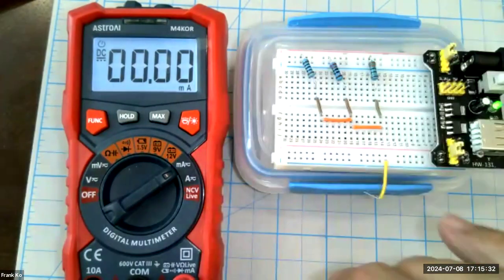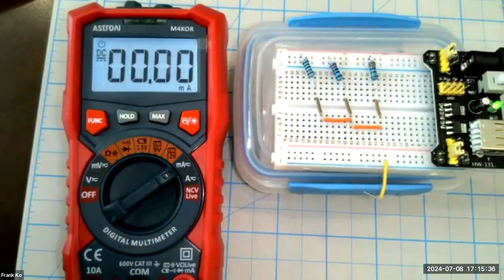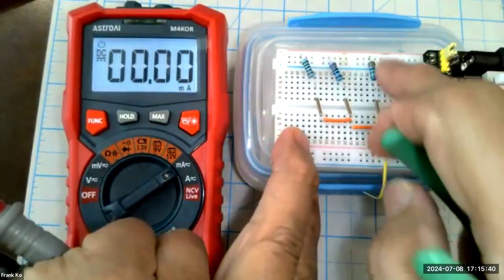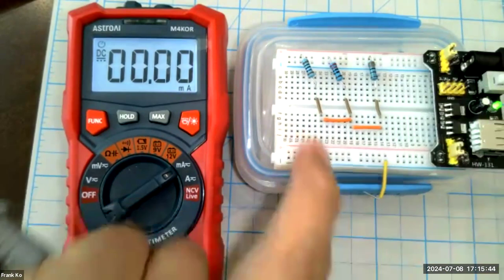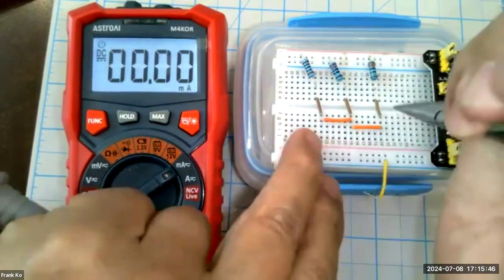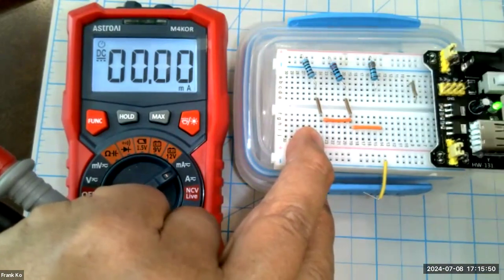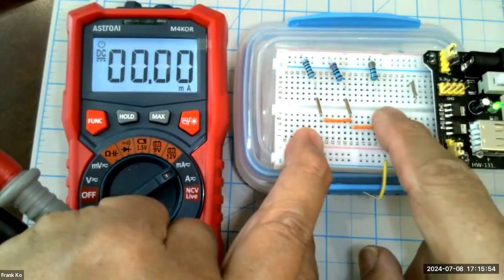And again, the neat circuit building allows me to very quickly make these measurements. And very quickly, the first fault condition was something occurred in this path for the R3 where it's either burnt out, miswired, whatever the case. I can replicate that fault condition simply by removing this jumper and setting it aside somewhere else. I now have an open. This R3 is no longer part of the circuit.